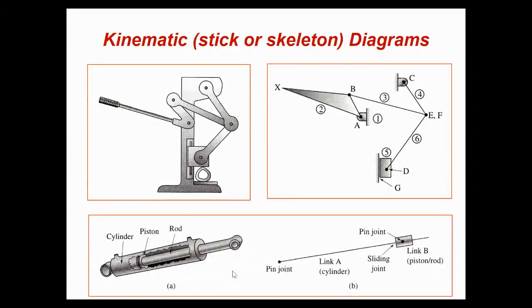And also, if you have something like a hydraulic piston or pneumatic piston, we replace it by a sliding joint moving on a rotating joint, kind of.